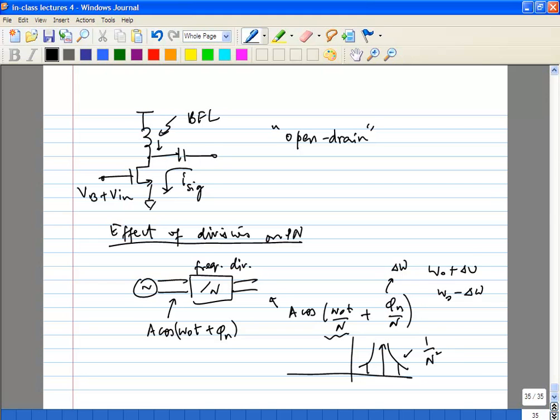Yes, it will be a square wave. It could be a square wave, it may not be. If you implement a digital divider, like a CMOS divider, it will be a square wave. You could also have tuned dividers, analog, CML kind of dividers, which need not necessarily have full scale amplitude. But it doesn't matter, because you can model the divider as some frequency division followed by some amplification. So your noise will also get automatically amplified with it. The change in amplitude will not matter too much for your phase noise itself.